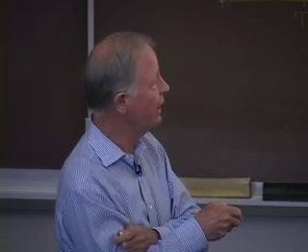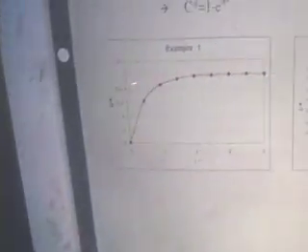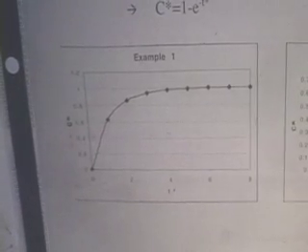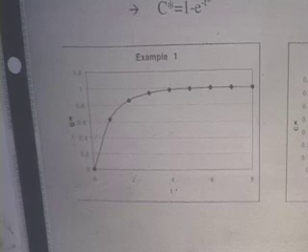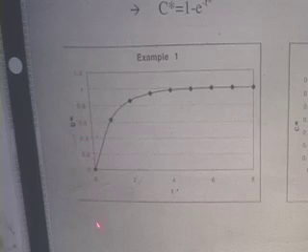A T star. So now I can come to my T star plot, and I come over here, let's say it's T star of 2, and I read a C star of 0.84. How do I turn the 0.84, which is dimensionless, into something that has dimensions? Multiply by C0. So embedded in this,